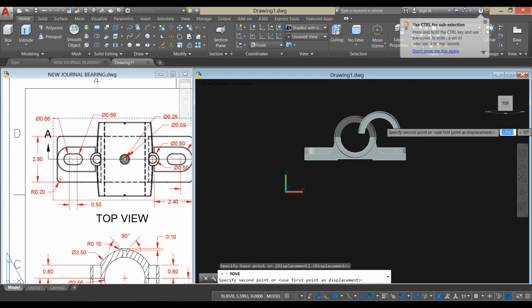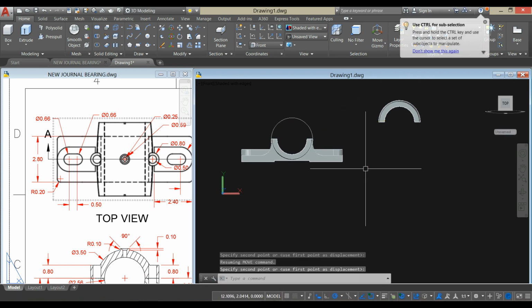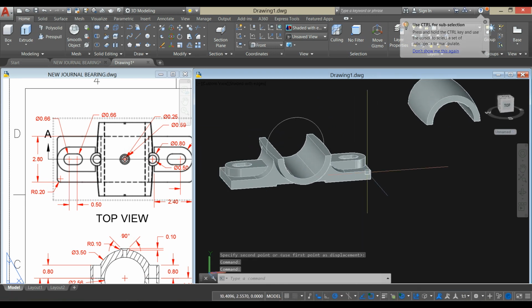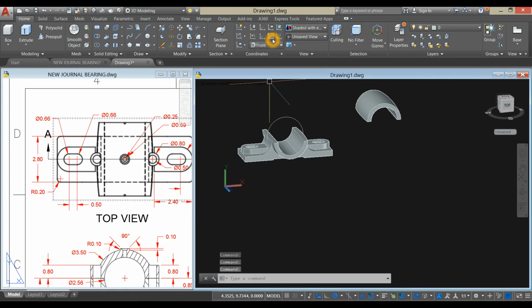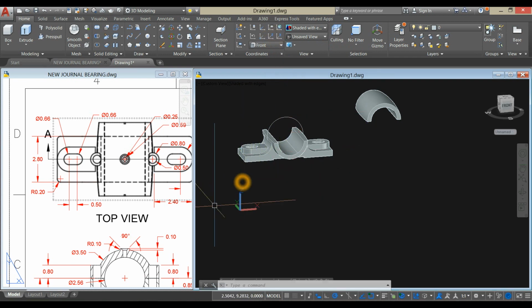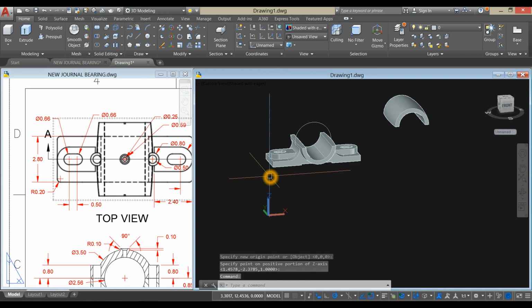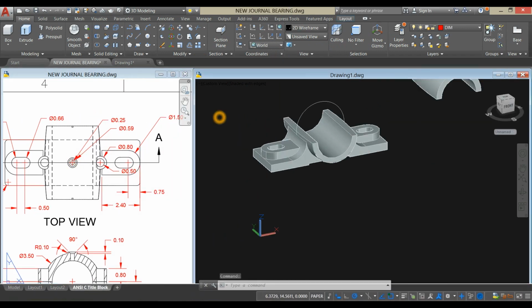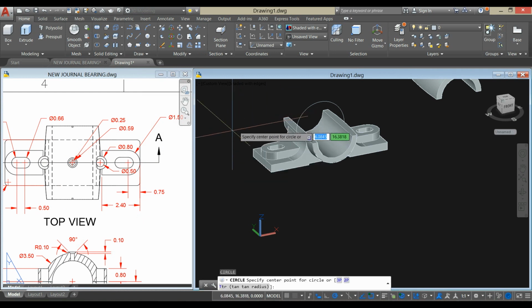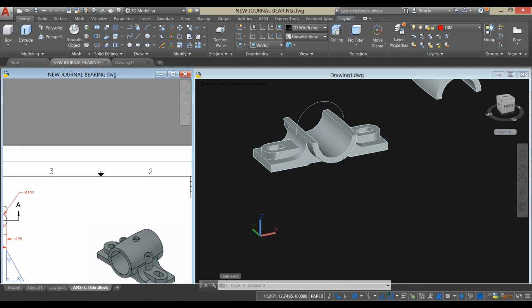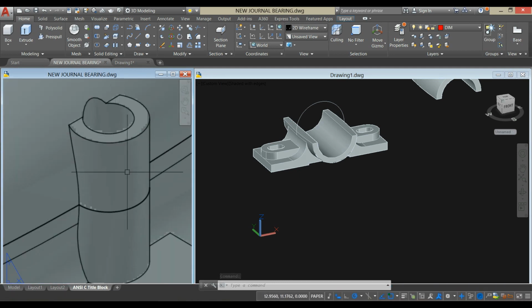We're gonna move this one. Change the direction of your Z. So go to coordinates panel and bring your Z upward. Type C for circle command. And the diameter for this outer circle here is 0.8. What we are gonna create is this cylinder here.